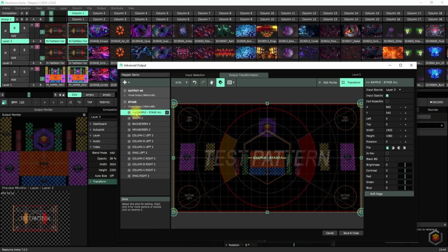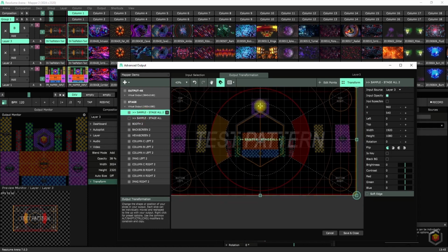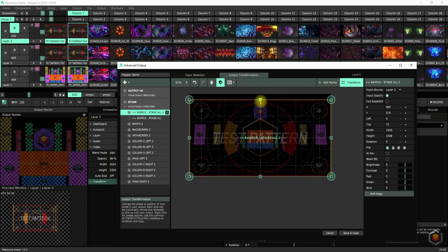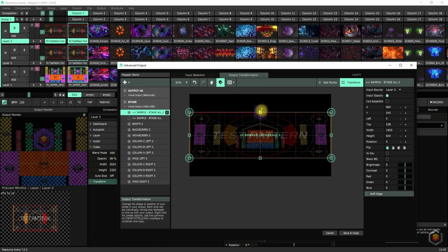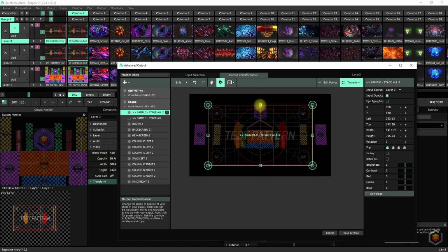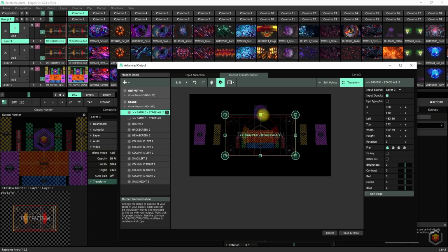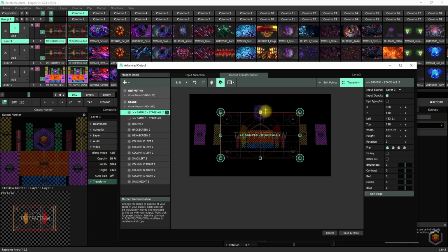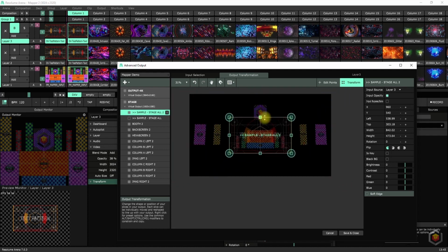So let's duplicate it, hide the other one, and in this case let's do something only for the center. You can drag while holding Alt, it will do the other side, and Shift as well, then it will keep the proportion. If you see, I'm snapping because this is on, but if I hit Control as well, it will not snap anymore.